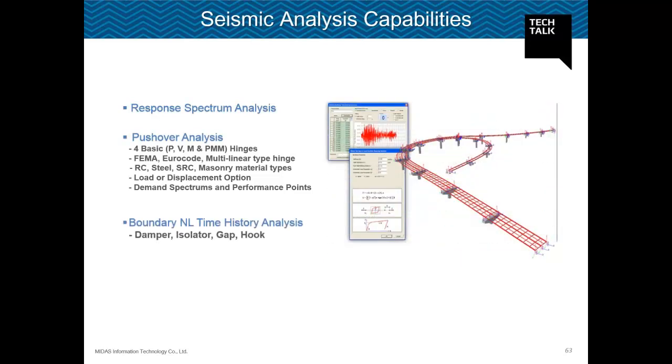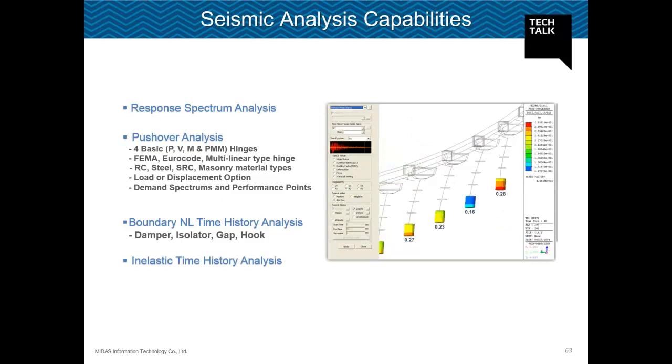And we have the boundary nonlinear time history analysis as well, to include the dampers and isolators or gap elements and hook elements. And there is inelastic time history analysis as well, which we can perform for major earthquakes to make our structure very, very safe.